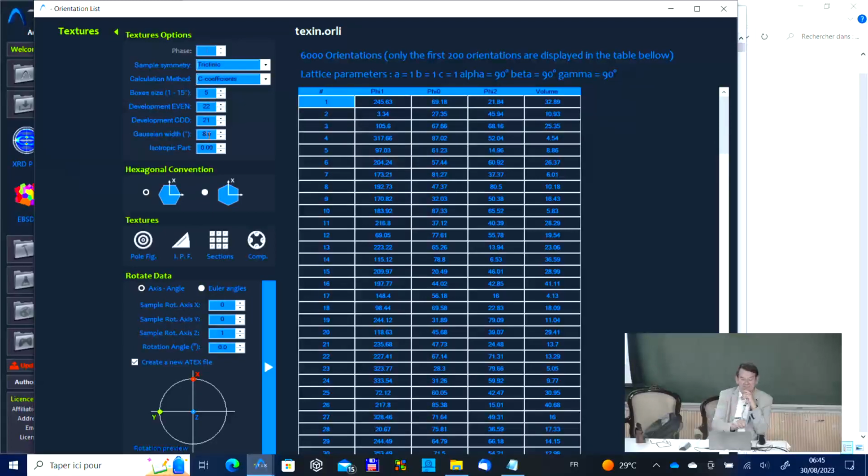If we change these 8 degrees to smaller, then we will have a more spotty representation, and as we increase this value, we will have a more even one. The 8 degrees is a standard choice, but it's possible to make other values, like 5, even 1, whatever you want. 8 is proposed.